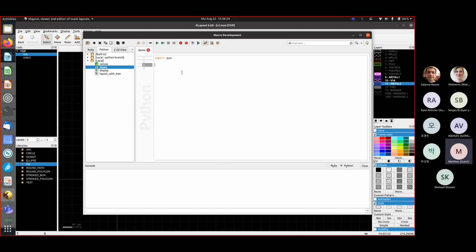I know that people have asked a couple of times for using some system environment, which on Windows is not available, but I could use Conda, for example. I already tried myself. I can basically build against Anaconda. But if I would deploy this way, then you would always have to install Anaconda plus KLayout, otherwise it wouldn't work. And it's a bit of a trade-off. People like self-contained applications, and that's why KLayout comes with its own kind of partial Python.